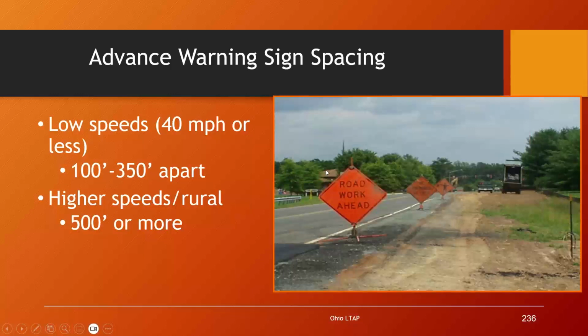In typical application number 10, we see a series of signs, and then of course the top table on page 17 of our guidebook or the app under spacing is all about how to properly space our signs. Looks like in the picture here, I'm just going to guess that's 100 feet between signs.